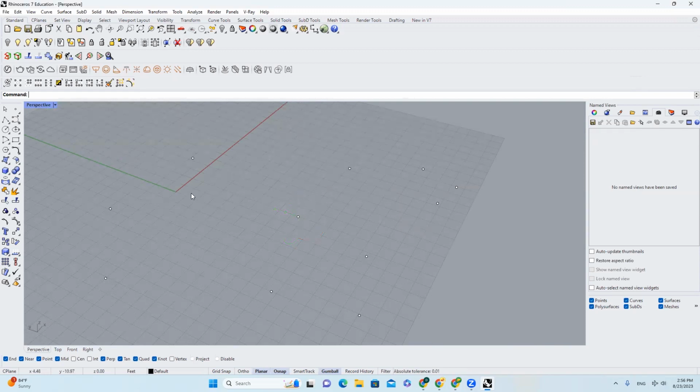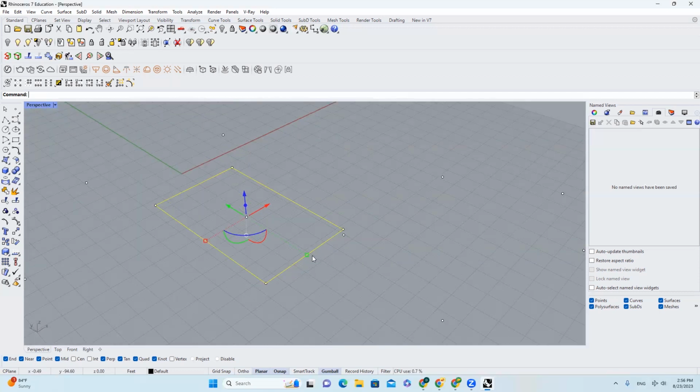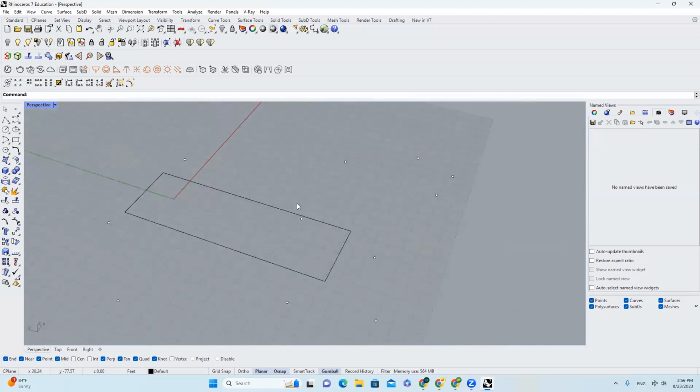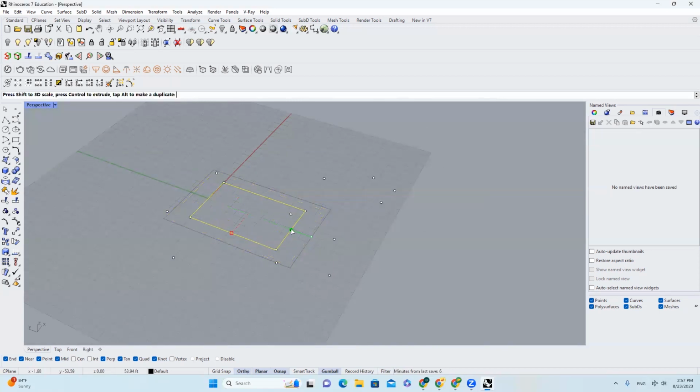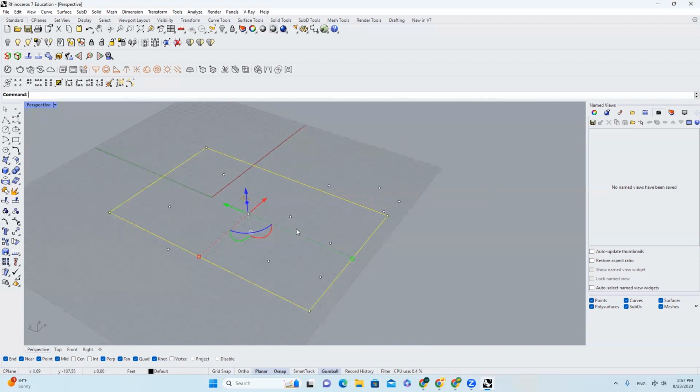Also, if we are making a complicated shape, let's say a rectangle, I will select this. If I want to scale this in the Y direction by 2 times, I would just click this little rectangle here and type 2. If we want to do that in this direction, which is the X direction, we will do 2. It will just scale in that direction by 2 also. But if you want to scale everything uniformly, all you have to do is select this, hold shift, and drag it around. Okay, so that's what you need to do.